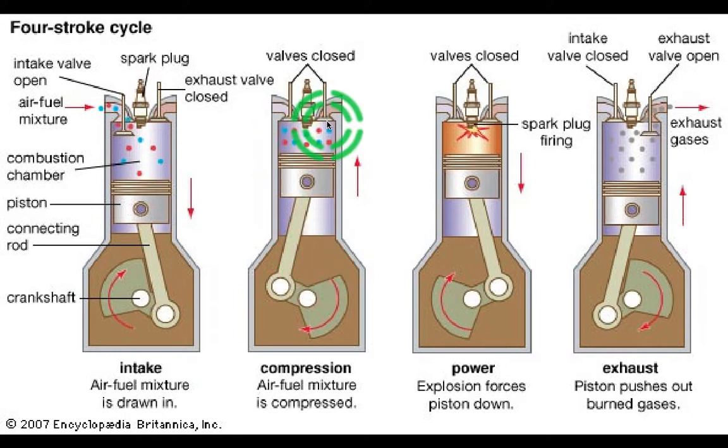So what's going to happen if you close both the valves and the piston is going up? It's like the syringe is going up and you have stuck your finger at the tip of the needle. You're going to be compressing it. That's exactly what's going to happen at this point, when the piston is forced up, say by the starter motor, and it gets compressed.